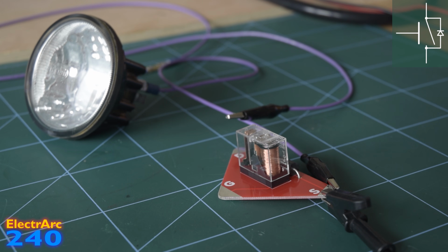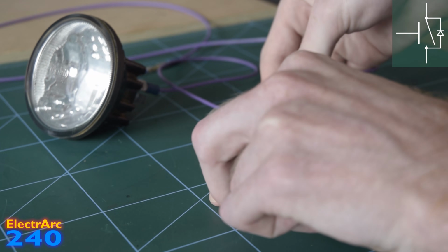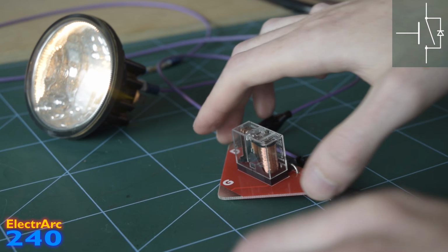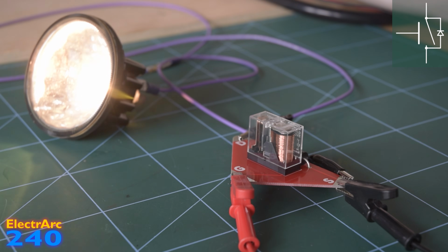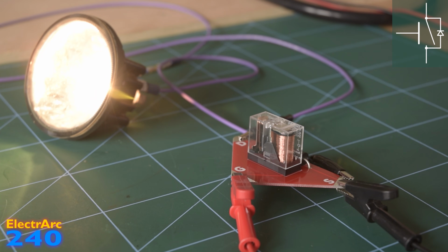That's because the body diode is not as good a conductor as the channel. So if I hook the lamp on permanently and then connect up the gate as well, you'll see that when I apply a voltage to the gate, the lamp gets brighter. And that's because with the MOSFET on, the current is all flowing through the channel, which is a much better conductor. So although the body diode means that current can flow all the time between the source and the drain, it's still important to turn the MOSFET on if you want current to flow in that direction, because it will be a lot more efficient.